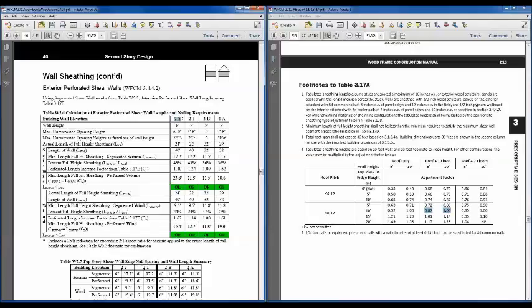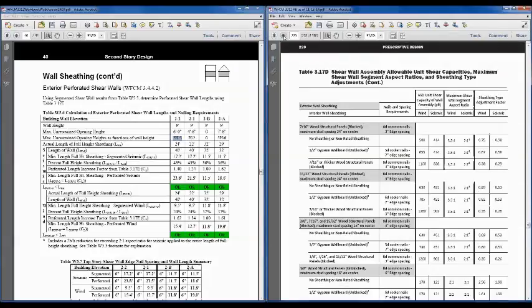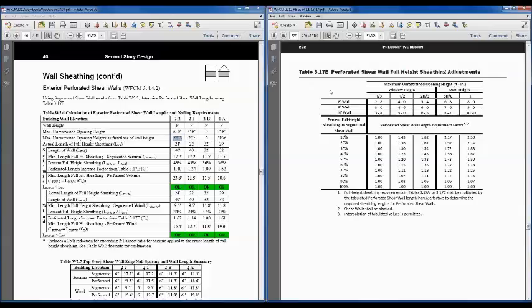So we're going to again look at the 2-2 wall. The maximum unrestrained opening height in this wall is 6 feet. That's that large bathroom window in the center of the wall. And so that gives us 2h/3. I'm going to jump then to table 317E. That's about the easiest way to go in the wood frame construction manual.